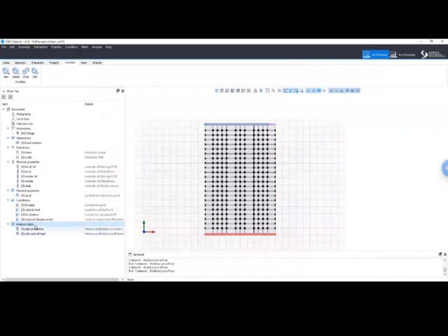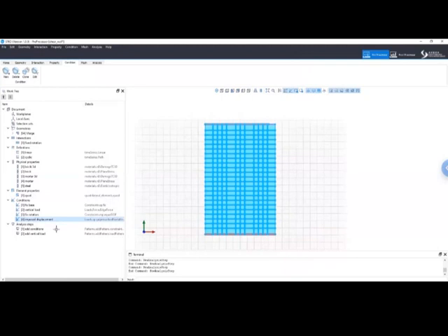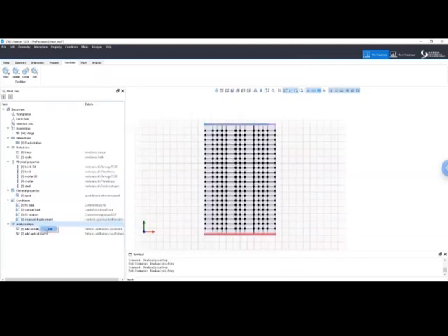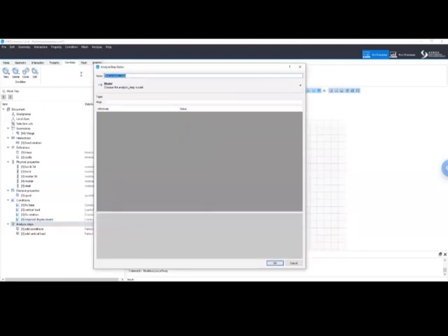Now, as you can see here, we applied the fixity, the multi-point constraint for the fixed rotation of the top beam, and the vertical load. We didn't apply the imposed displacement. Why? This one will be done in a subsequent step. Now we need to do the vertical analysis. So we go under Analysis step, Add, and we call this one Vertical Analysis.